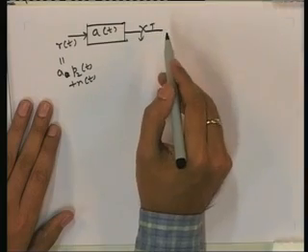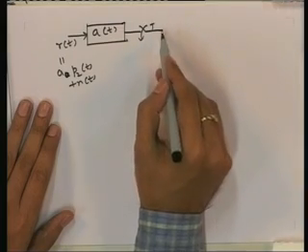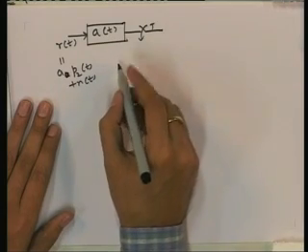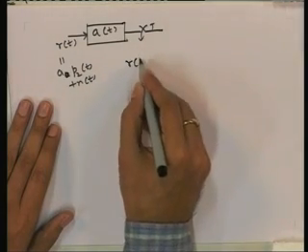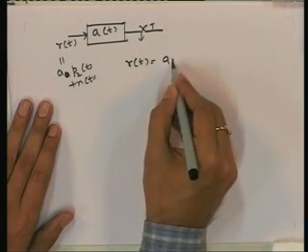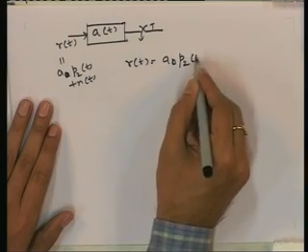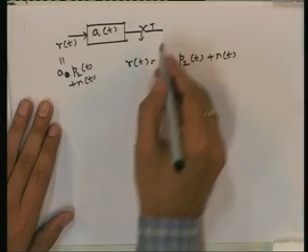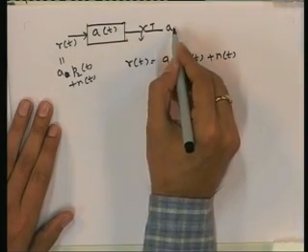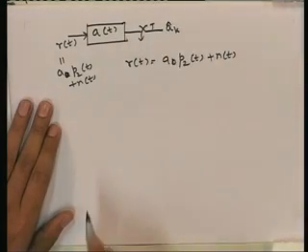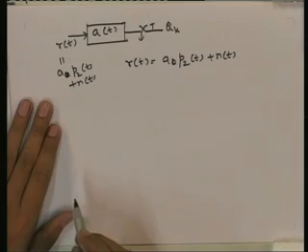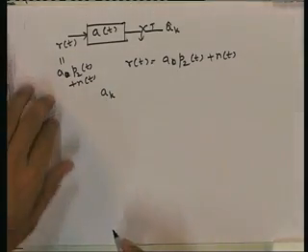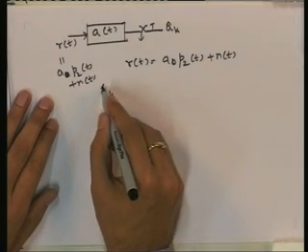So we will see what is the best filter to take to maximize the SNR here. The energy of the signal part divided by the energy of the noise part should be maximum. So what should be my A(t)? That we will see. So our r(t) is A naught p(t) plus n(t). Now we will assume that we are taking A_k hat, the estimate of A_k that we want here. So what is the estimate?